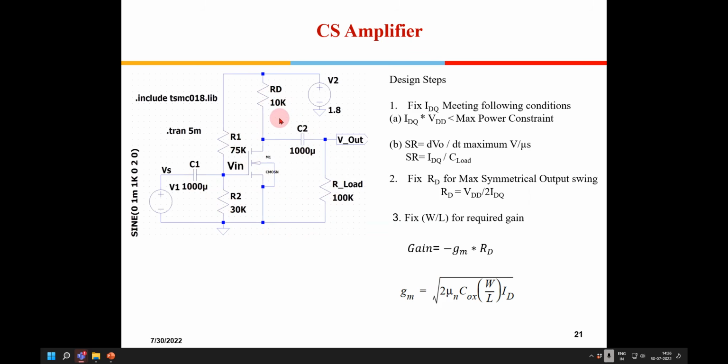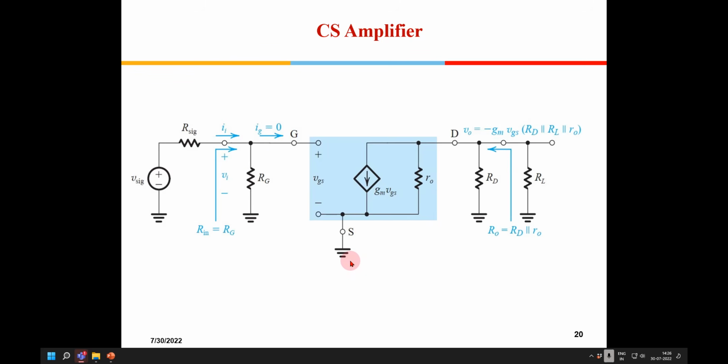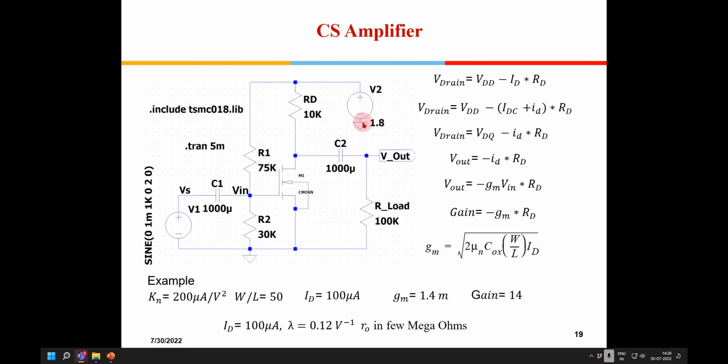I have one doubt, sir. There are some rules regarding converting the transistor model to a small signal model, right? Can you briefly explain those rules? No, this is the model, this is just gm VGS. All the DC voltage sources will be grounded, and current sources will be kept open, and capacitance will be shorted. If there are inductors, those will be kept open. Okay, sir. Capacitance short, inductor open, voltage sources short, and current sources open.